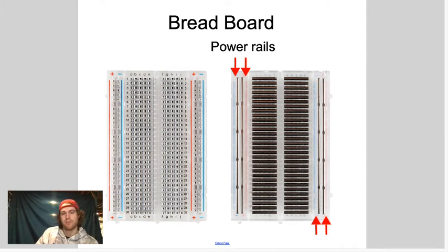So it allows you to make connections and order things and keep things organized without having to use a whole lot of wires. So how a breadboard works is you can send electricity to something like this, and you see how those rails are connected all the way up and all the way down. This positive rail is not connected with this rail. It follows the connections that are listed in this picture. So these ones run vertically, these ones run vertically, and these run horizontally.